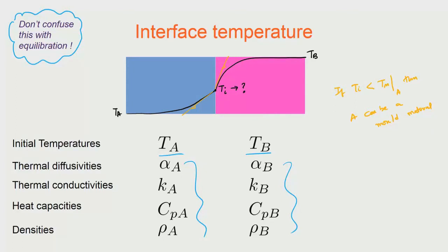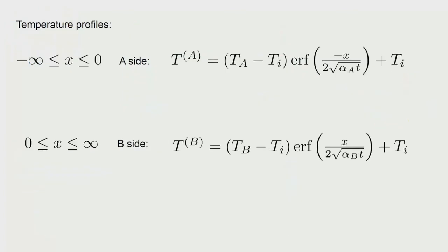What we do is that we see that in this situation, the way we have drawn these two curves, we can imagine the error function solution available here in these domains with these scaling factors. So, one scaling factor comes out as Ti minus Ta, and another scaling factor comes out as Tb minus Ti, and other than that the error function is straight away applicable. So, we go ahead and apply error function to these temperature profiles and see what can be reduced. So, we write the error function solution here. For the left hand side of the domain, we write it in this manner.